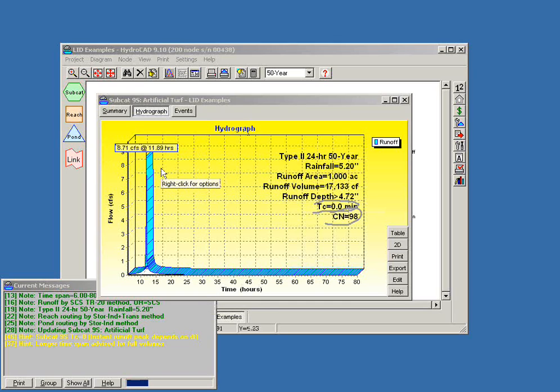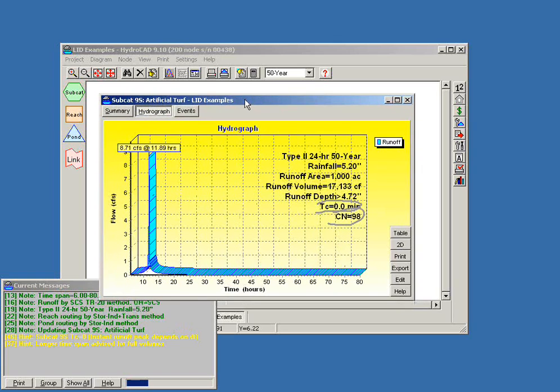However, the peak flow here is really not a critical factor because we are taking that flow and it is going through the turf and immediately into the porous base layer underneath. So we don't have any kind of piping or other system that actually sees that flow. The flow is distributed over the entire surface.